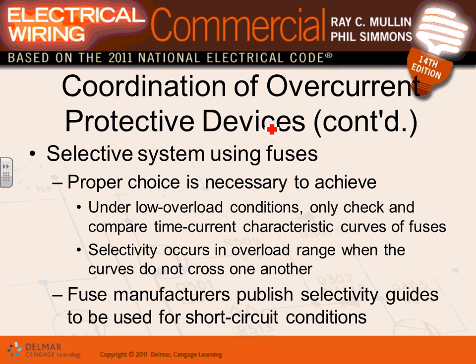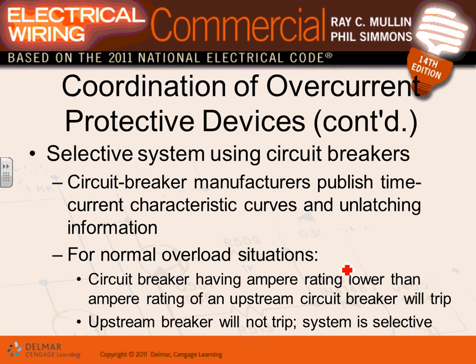And of course, manufacturers of circuit breakers and fuses always give you a selectivity guide. You'll see a couple of them that tell you, use this circuit breaker with this circuit breaker. We guarantee they are going to select. They will have selectivity. So it helps you to do that.